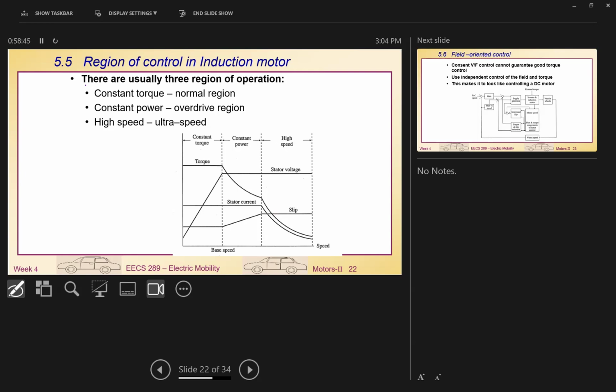So basically from 0 to 60 Hz, then proper up to 120 Hz, and going further, you weaken further and lose performance. But that's quite okay, because at high speed we usually rely on momentum to drive the vehicle. At this time, much of the frictional torque can be reduced. You don't have the static friction, so the motor is able to run at high speed anyway.